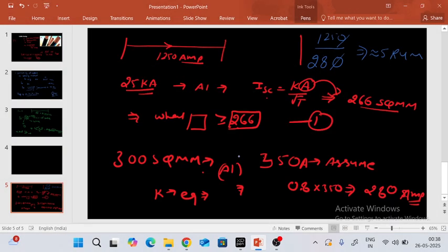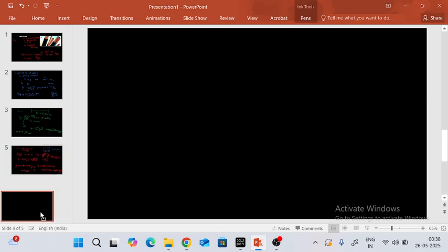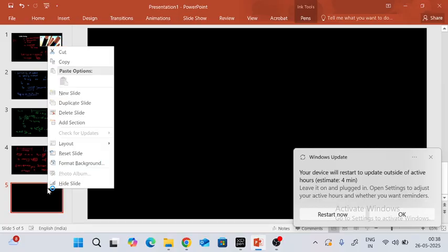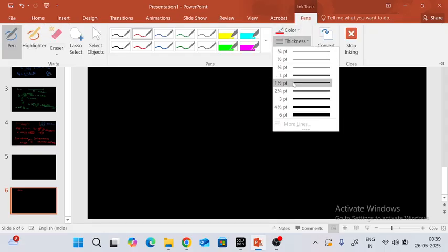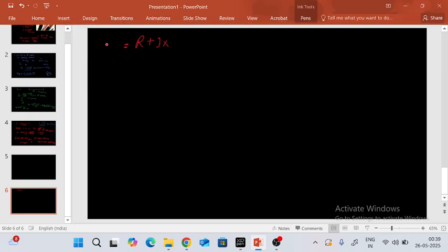Now all of this is done, but we have to check one important thing, which is associated with the voltage drop. When I talk about voltage drop, it basically equals the loss of the cable. We are talking about the efficiency of the cable, because the cable has some resistance R plus jX. I mention R plus jX because it equals Z equivalent of the cable. There is some resistance and some reactance, plus the concept of capacitance.